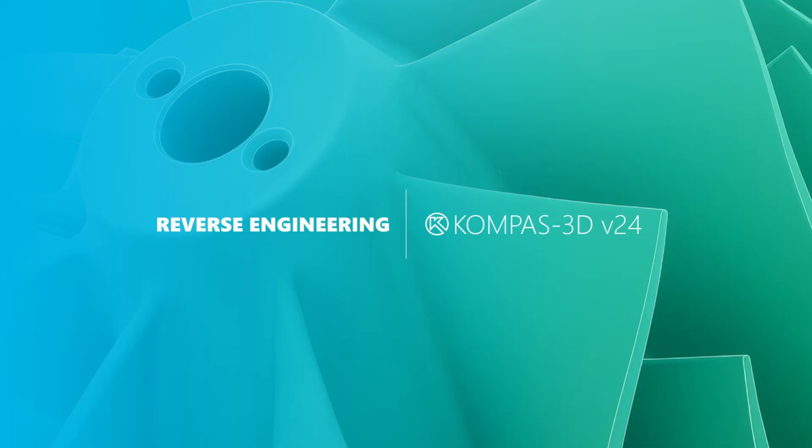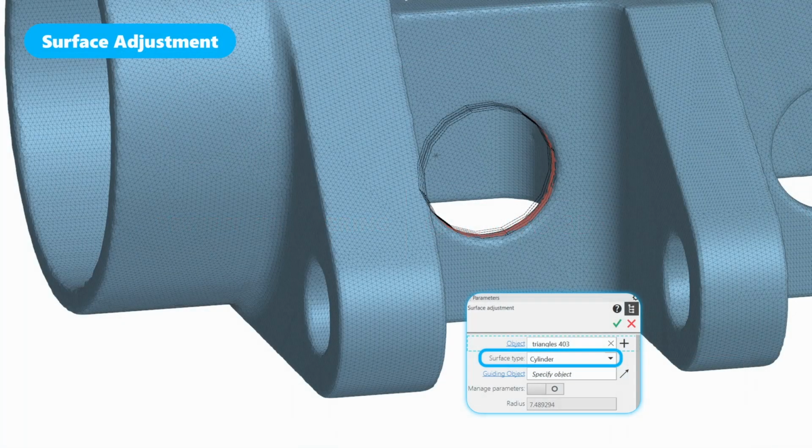Reverse engineering is a key theme for those who work with the results of 3D scanning or recreate critical parts when original documentation is missing or the manufacturer no longer exists. The surface adjustment command defines the surface type automatically based on the selected area. Available surface types include plane, cone, cylinder, sphere, torus, or spline.